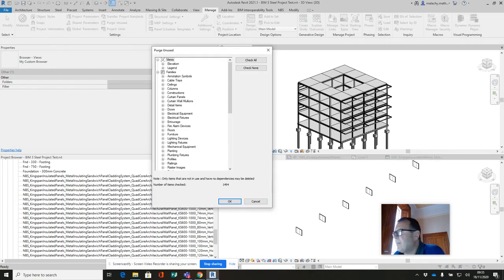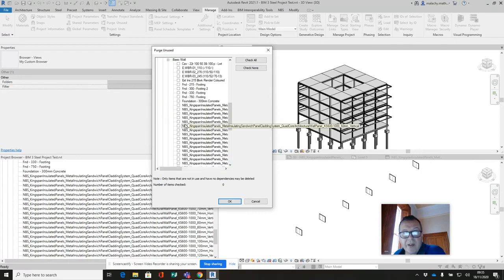Now, be very careful when you use purge unused, and I've got a little video on my YouTube channel about that. First thing you're always going to do is check none, because you can see that these are checked, and they are by default. Now, when I hit check none, none of them are checked. So I'll go into walls here. Yeah, super. So I can go in now, and I can purge out ones that I don't particularly want.